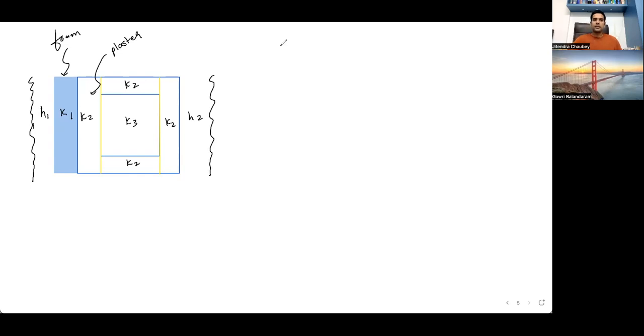Over here, if you try to draw the electrical analogy first, it will be exactly the same as what you have sent me. This is convection, this is conduction, conduction, three in series, then a parallel of conduction. Then this is conduction, this is convection. So I draw convection, then conduction, three layers of conduction in parallel, and then again conduction, and then again convection.